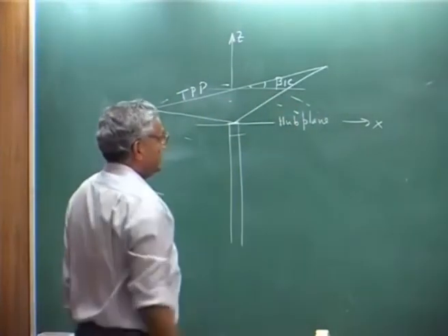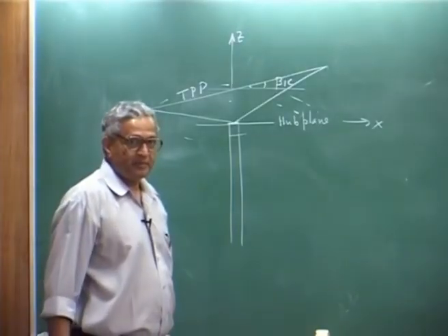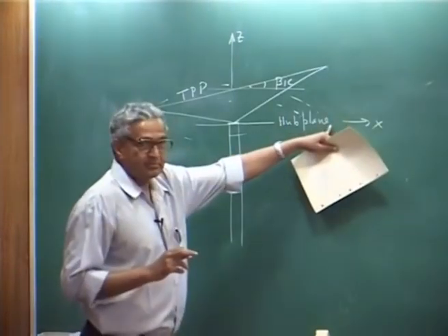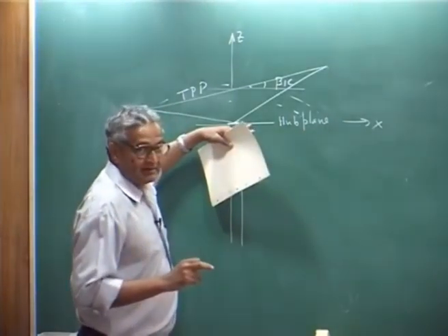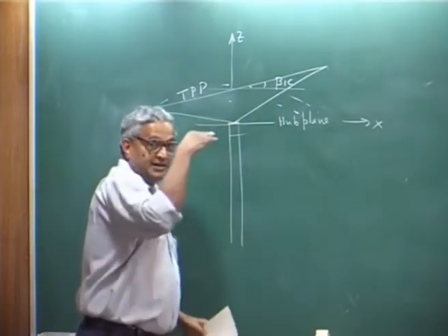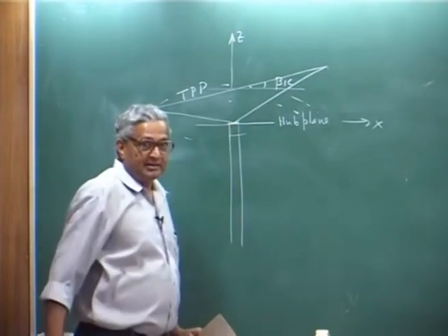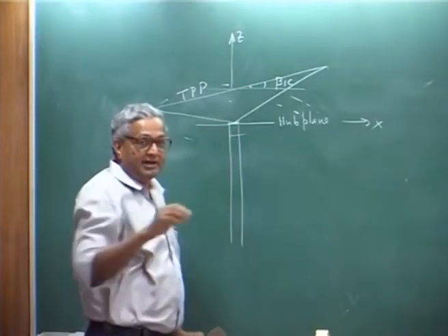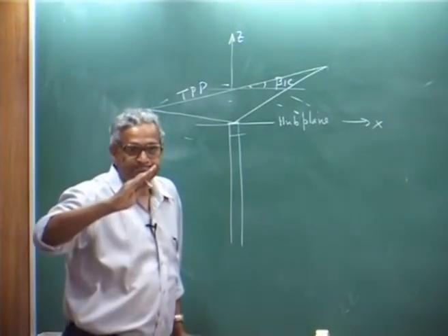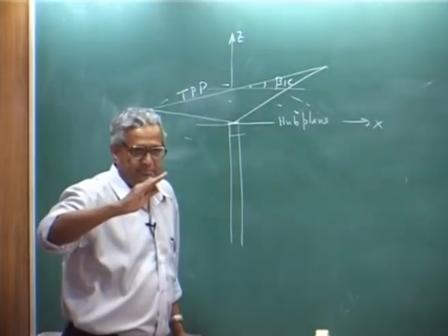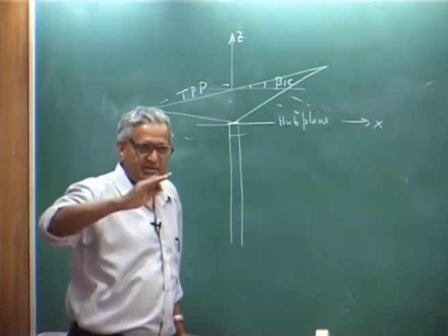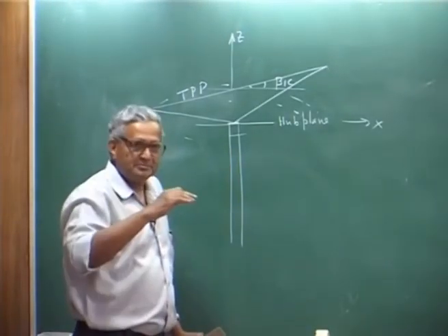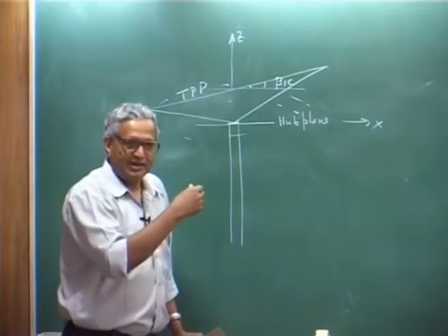No feathering plane means I am giving a theta 1s, because in this I am looking at it this way, in this y direction. The pitch angle I give when the blade is at 90 degree, I give a theta 1s which is positive. You assume that you are giving a positive pitch angle, and then when it comes to 270, you give minus, because sin 270 is negative.